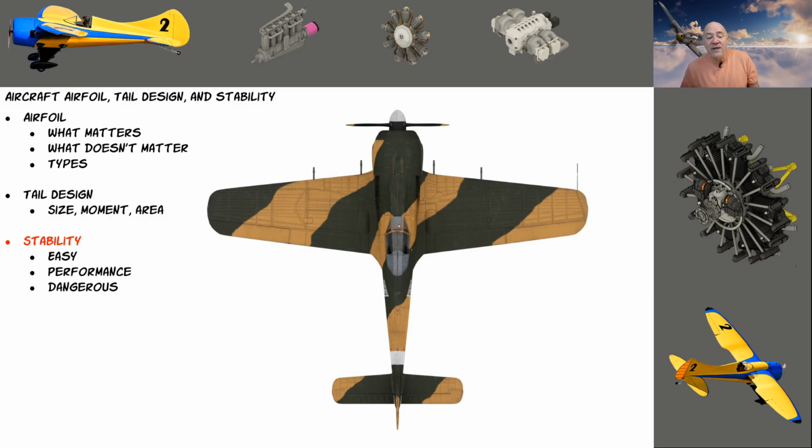I love the 190, okay? And one thing I love about the 190 is it's got a long tail, and the nose had a big radial engine in it, so a lot of that was to get the CG right. But by having a long tail, it was a very pitch stable airplane.